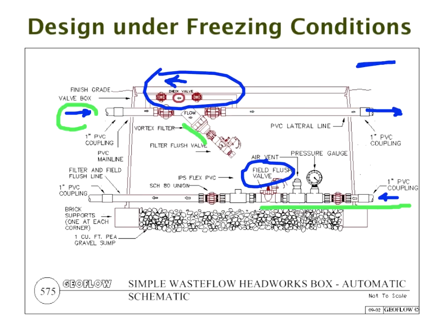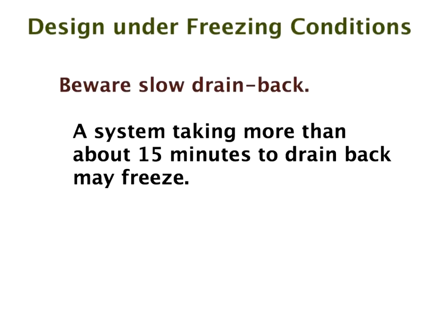So by having this bypass, the supply line can drain. I hope that's a little more clear. You can put in a solenoid valve here too, incidentally. You open the solenoid valve, or even better, an electric valve, because solenoid valves take some pressure to operate while electric valves don't, which I'll come to when we get to a discussion on valves.